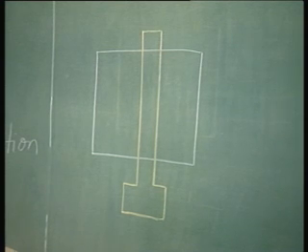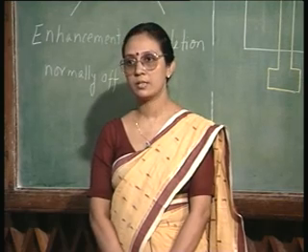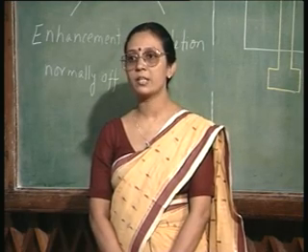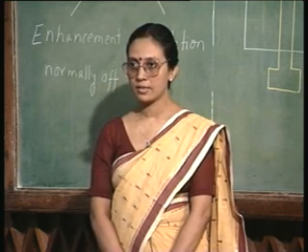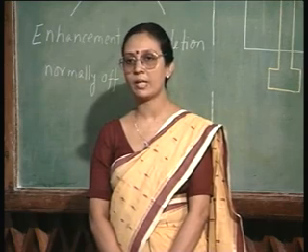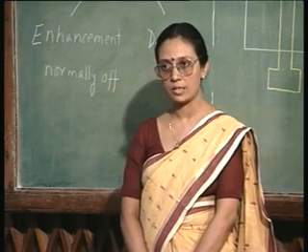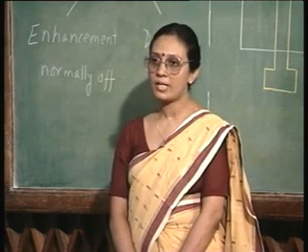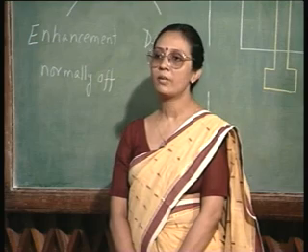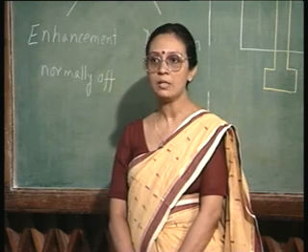No need to take this into account in the mask. So, you do not have any critical alignment. Source and drain are automatically aligned to the gate. Self aligned technology. Self aligned technology is a key word in today's integrated circuit technology. As the device dimensions become smaller, it is very useful to go for the self aligned technology, whereby the criticality of the photolithography can be reduced.